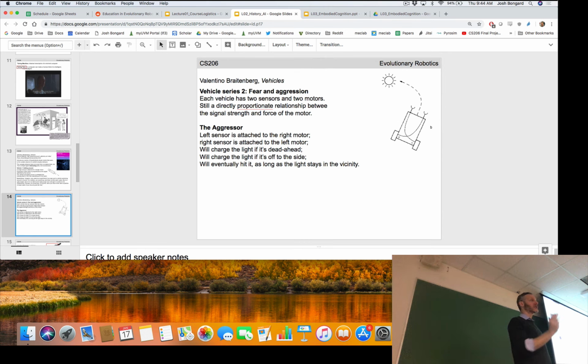It'll turn less sharply, so it'll start to even out its curve and start to head towards the light. What else can you tell me about the behavior of the robot, given what I've told you about its insides so far? It turns towards the light and straightens out. What else happens? It moves towards the light. It'll move a little bit towards the light, and then what happens? It'll speed up. It moves towards the light, so the total amount of light falling on the two sensors increases. It will speed up, and if it's a naked bulb, it will smash into it and destroy it.